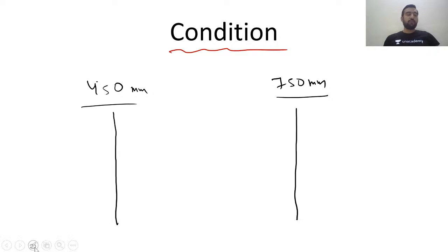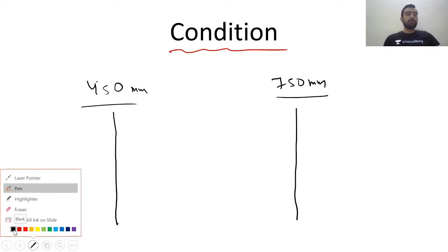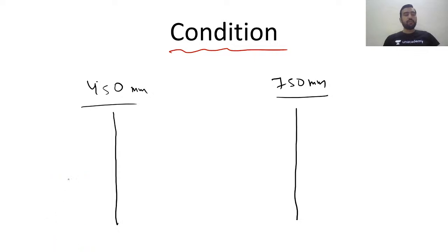now listen to me very carefully. So when you actually are in need of side reinforcement, suppose guys, if your beam is subjected to torsion and the depth of the beam is between 450 mm and 750 mm, if the overall depth of the beam is between 450 mm and 750 mm, then you have to go for side face reinforcement.